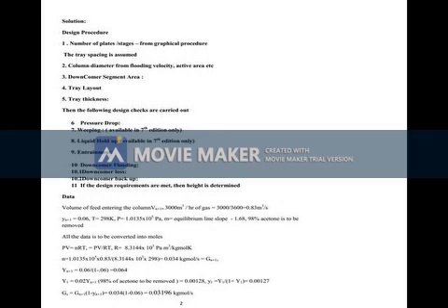Like that, G3, G2, and G1 is the gas coming out of the tower. Gn plus 1 will enter, because I told you Gn plus 1 is a fictitious plate. Such a plate does not exist, but we assume it is from the storage. Where is the gas coming to the column from? It is coming from a storage tank through a pump or whatever way. So Gn plus 1 represents the storage tank.